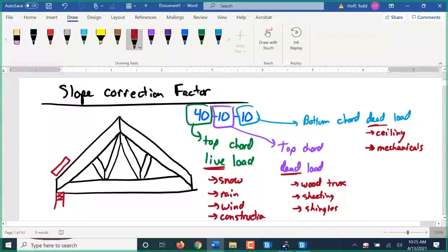A lot of times they'll put an air conditioning unit or air exchanger up in the trusses in the attic of a house. When they do that, it has to be planned to either have a wall supporting it underneath, or they have to specially design the trusses in that portion of the house to handle that extra load. See, a lot of people retrofit a house with an air exchanger in the attic. They don't figure that in, and it causes problems.